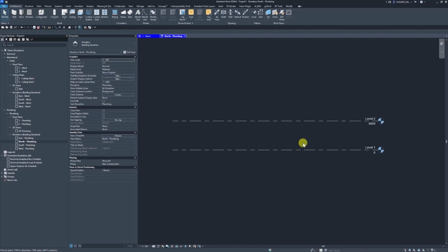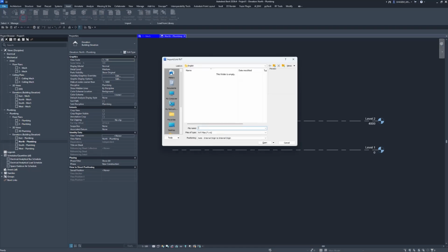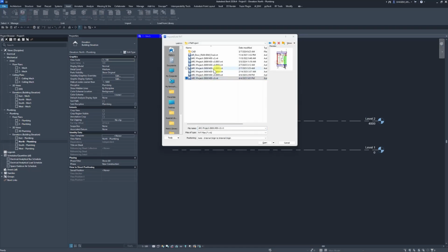Now, one more time, guys, the project that we want to start is HVAC. So, for doing that, we need to be linking both the architectural model and the structural model in our template. How can we do that? Well, surely you already know. From the Insert tab, click on Link Revit. Then in this tab, select the required file and click on Open.